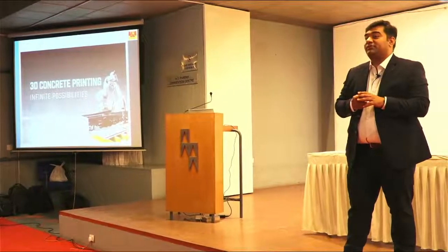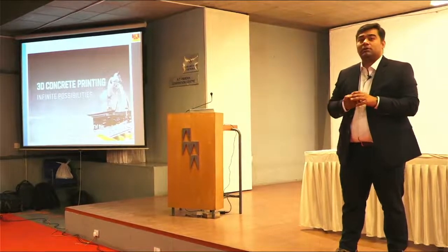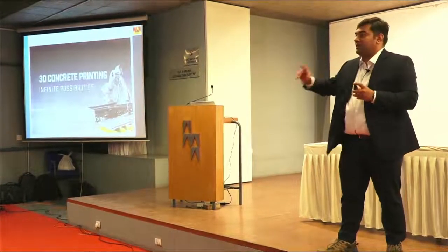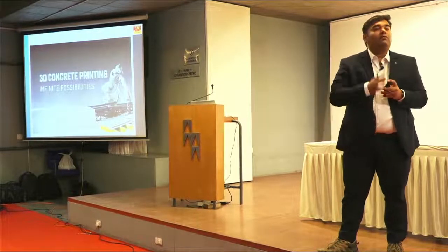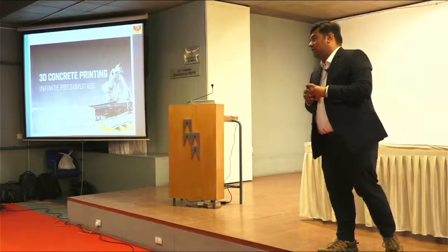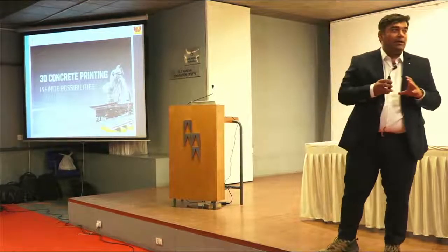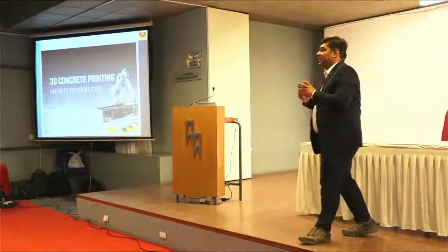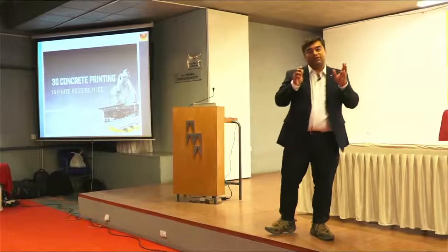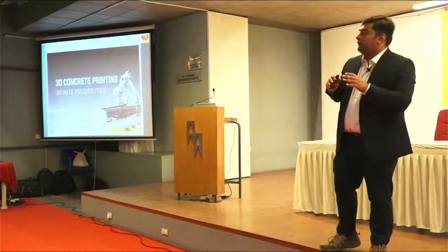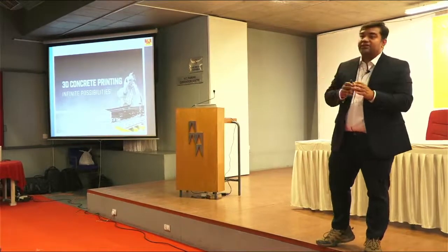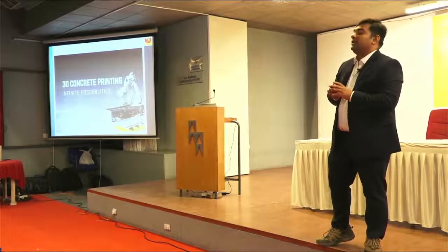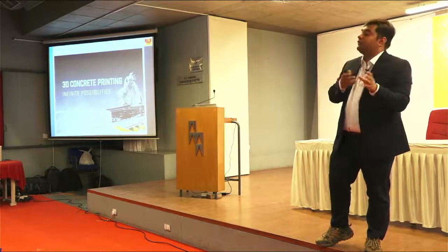What were the final 2 steps? Placing and curing. Curing and finishing. This requires minimal finishing. The only thing left is curing, and in the next lectures, you will come across various products which do not require any curing. This technology is still under development. If this concrete does not require any curing, this will be the future of RMC.